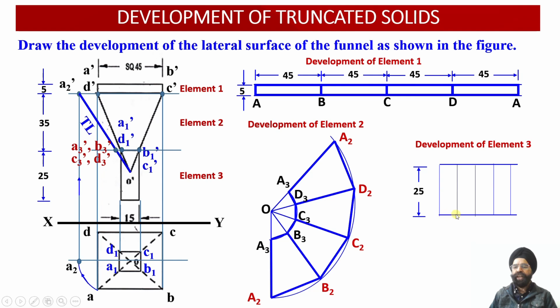Now corresponding to the four faces, again we are going to start with point A. So it will be A1, B1, C1, D1 and A1. So 5 points we have marked over here, which are going to represent four surfaces of the square prism over here. Now the edge length between A1 and B1 will be 15 millimeter.